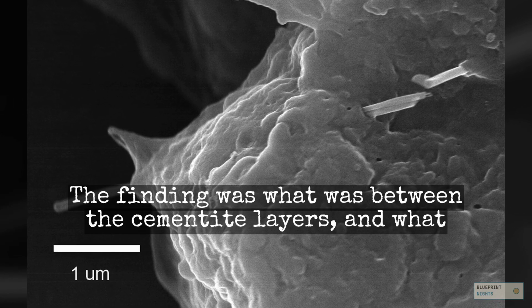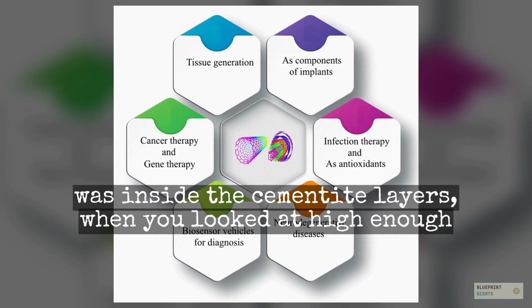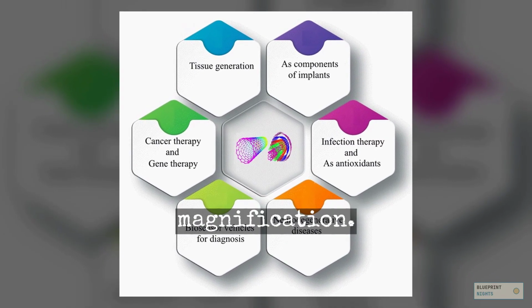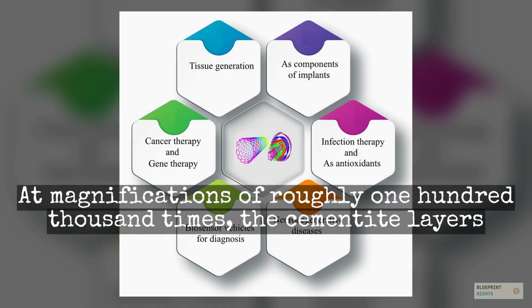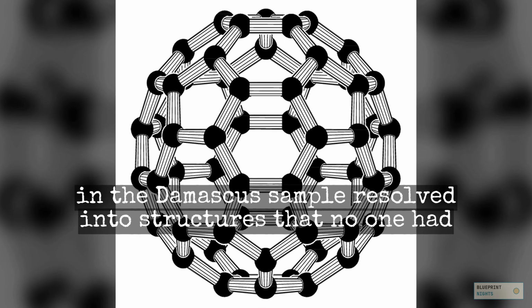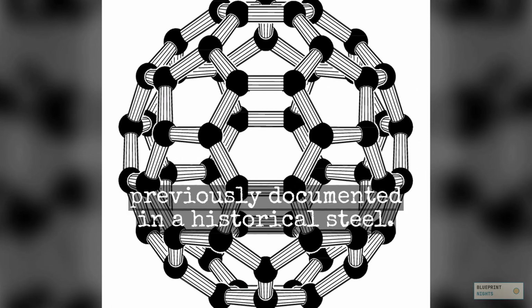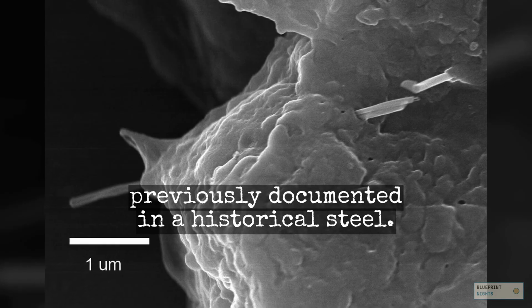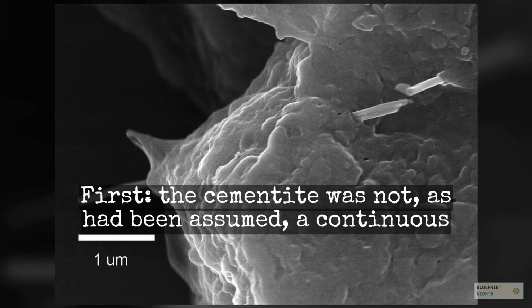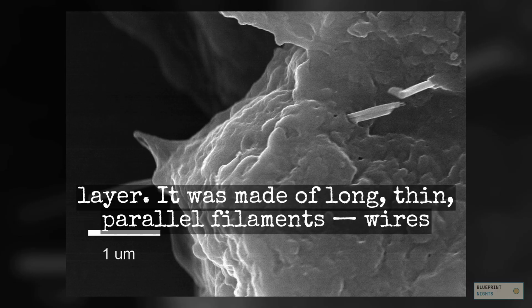The finding was what was between the cementite layers and what was inside the cementite layers when you looked at high enough magnification. At magnifications of roughly 100,000 times, the cementite layers in the Damascus sample resolved into structures that no one had previously documented in a historical steel. First, the cementite was not, as had been assumed, a continuous layer.